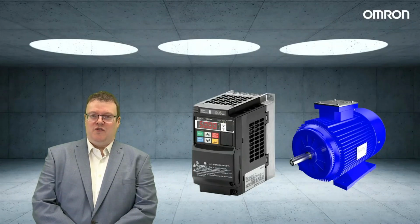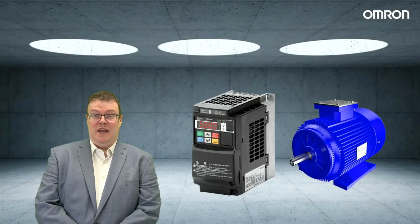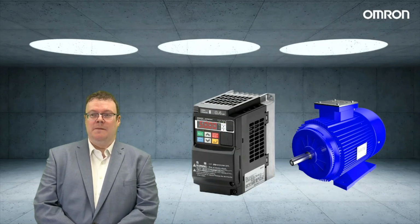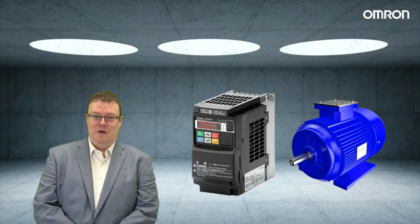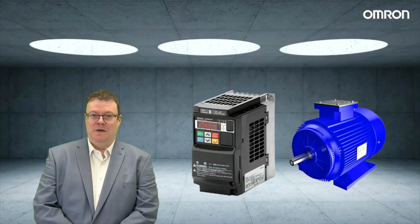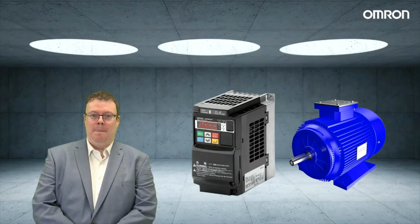If you think about a traditional direct online starter, when the motor, for example in an HVAC or air conditioning system, is started up, it immediately runs to full speed. If you then want to control the airflow, it has to be done through physical dampers or louvers being opened and closed. This is very inefficient in terms of energy usage. Another way to think about it would be, imagine driving your car and essentially running the engine at full speed and having to use the brakes to speed up or slow down.